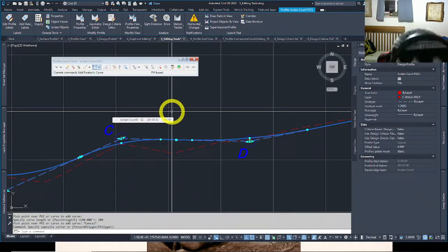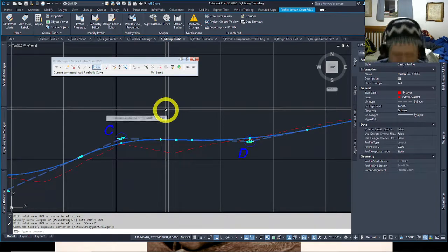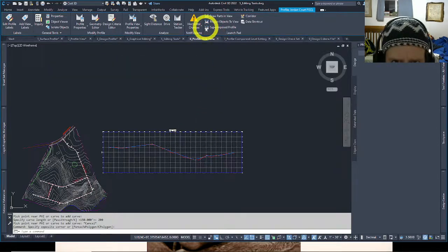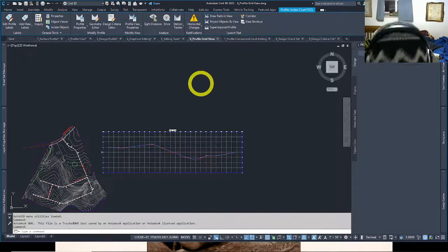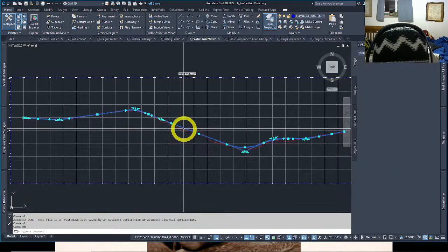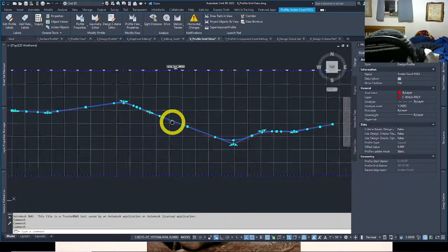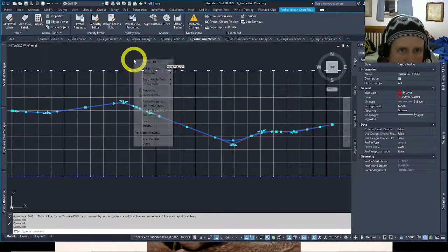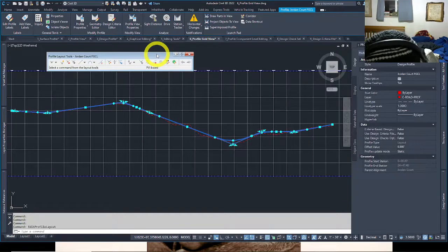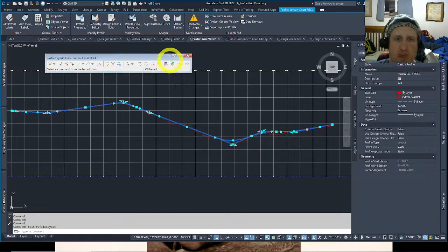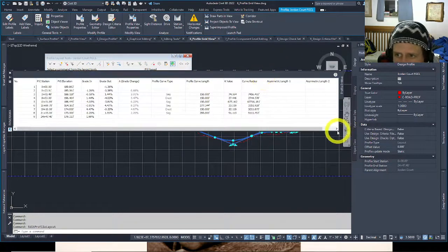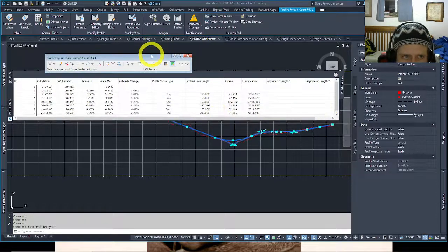We'll jump into page 142, editing a profile using profile grid view, which I just did here. All right. So let's go into profile grid view just to continue on. And we're going to go back to our Jordan FGCL profile again. And we can pick the geometry editor once again, or right click and edit profile geometry this way. So in the newer versions of Civil 3D, the icon has changed a little bit. It looks like this, but it's called profile grid view. It brings up the panorama into our event viewer, so we can do some deep graphical editing.